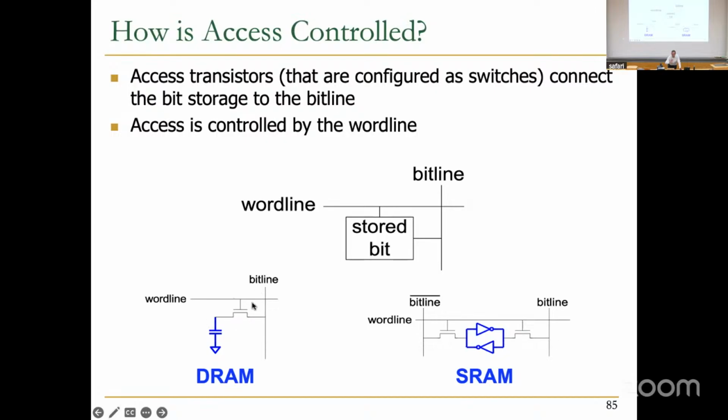The bit line gets perturbed a little bit because charge flows into it or out of it, depending on the voltage levels. And as a result, there's some perturbation in the bit line, and that can be sensed using some sense amplification circuitry. That's the idea of how DRAM operates at a high level, at least, without going into a whole lot of analog detail.